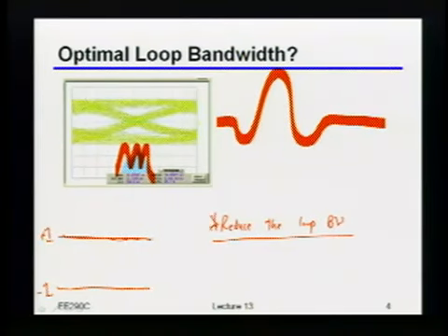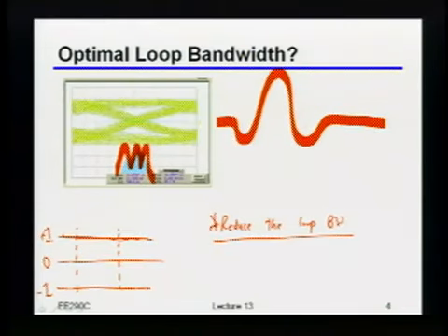I launch my 1 bit there, and I launch another bit right here, and the sequence I'm dealing with is a long string of zeros, a 1, and then a long string of zeros again. And let's say this is my 0 point right here. Well, if I've got a pretty bad channel, then I'm going to have this sort of exponential RC settling. So on that edge, it's going to look something like that, and then on the other edge, it's going to look something like this.